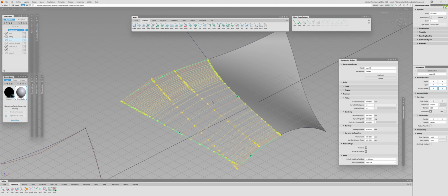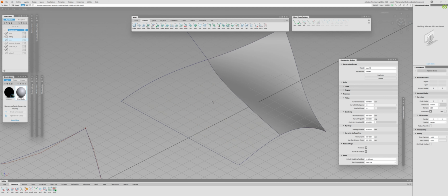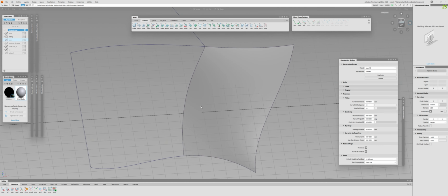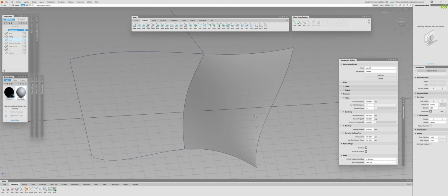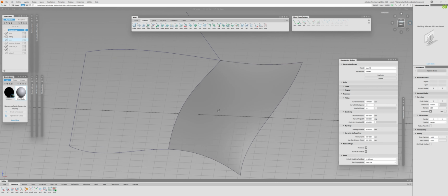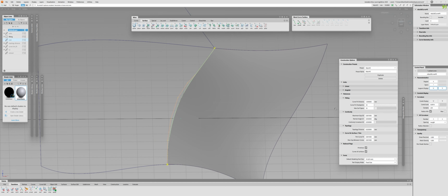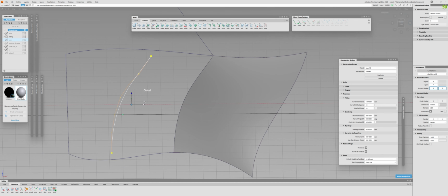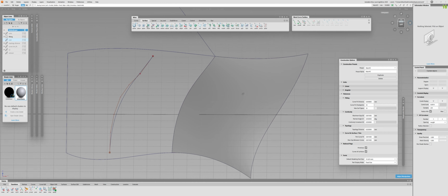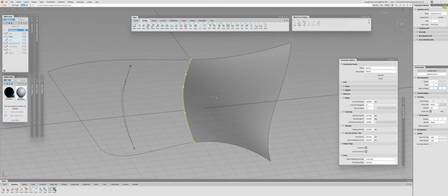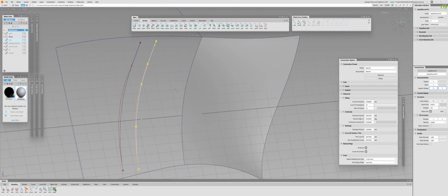All right. Now let's talk about the next parameter, which is the curve fit. Oh no, one more thing I want to show you about the curve fit distance is the duplication, because it relies on duplication too. Now let me go and, once again, loosen the tolerance, and I will duplicate the curve using the duplicate tool. Now if I look here, there is a 6 degree single span. You may already predict it's not positional. Now I will tighten the tolerance again, and then use it again. Look, it's now 6 degrees, 4 spans. It's much more complex.